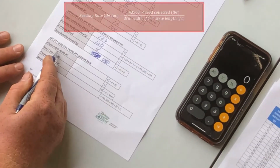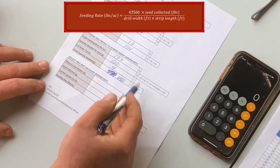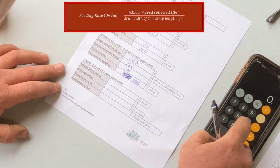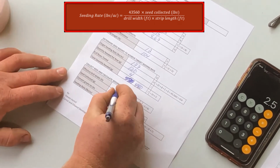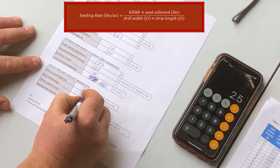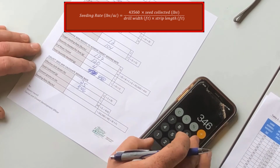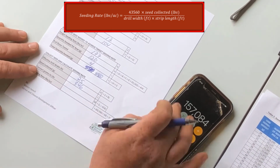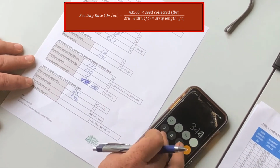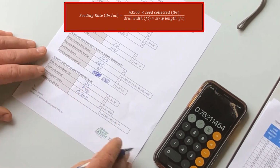So we got to figure out the effective drill width, which is I, which is 4 times B, which is the row spacing of 0.625. So 4 times 0.625 is 2.5. We collected 346 grams of seed, so we want to convert that to pounds. So we'll divide 346 by 454. So we collected 0.762 pounds.